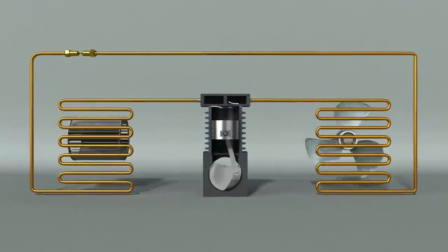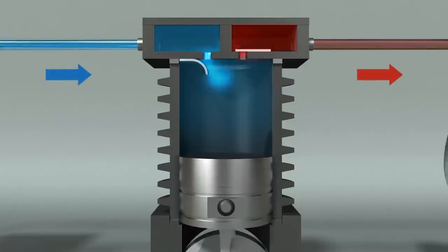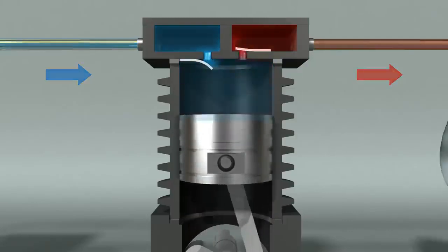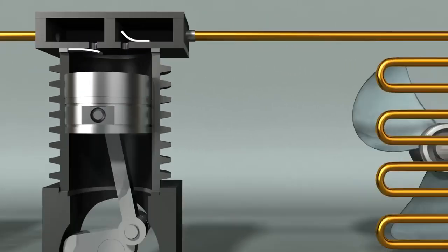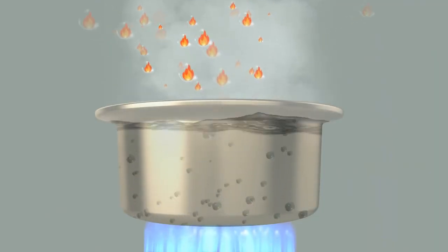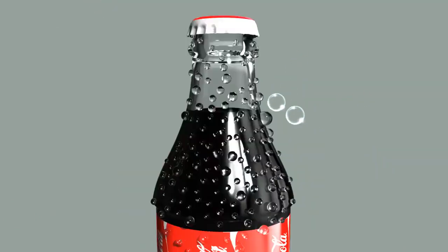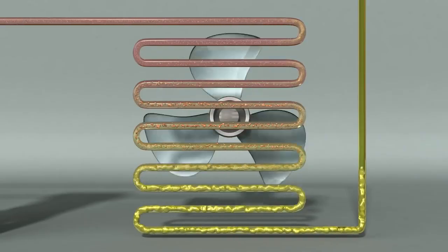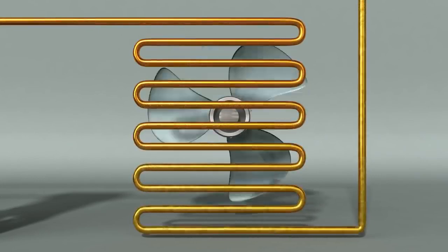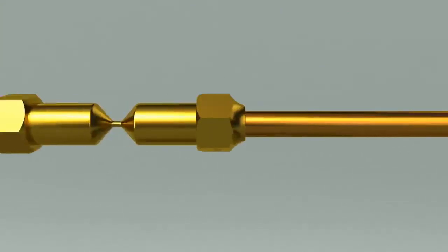First, let's look at the general flow. This is a compressor. If we compare a refrigerant to blood, a compressor is like the heart. A compressor circulates a refrigerant and compresses it to high temperature and pressure. Then, the refrigerant pressed by the compressor flows to a condenser. While evaporation is the transition of liquid to gas through heat absorption, condensation is the transition of gas to liquid when it loses heat. A condenser serves to turn refrigerant in hot gas state into liquid form by taking away its heat.